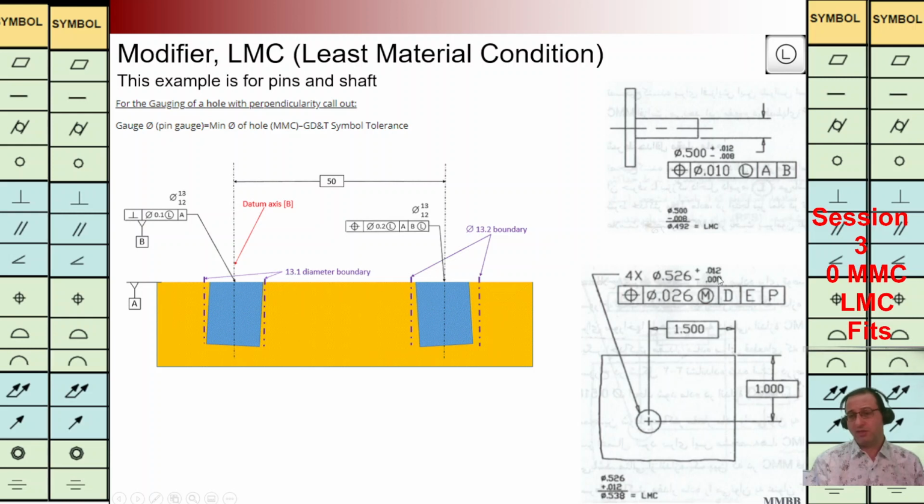In order to have least material on this hole, we should have the biggest hole diameter, and then we are going to calculate the summation of this diameter and the maximum value of the allowable tolerance. For that, we can calculate least material condition.